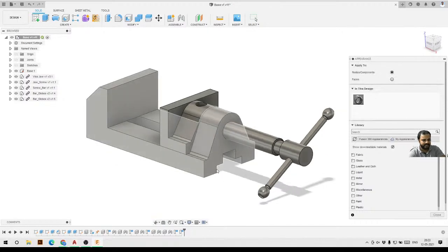But you always take care that whenever you are doing some actual product designing, just try to apply fillets on all the edges. Never leave any of the edges as sharp, right? Just apply a fillet of at least 1 mm, or at least a minimum of 0.8 millimeters, not less than that, if you are doing it for 3D printing. And even if you are doing it for rendering, apply a fillet of at least 1 millimeter, right? So that will be a very good practice.